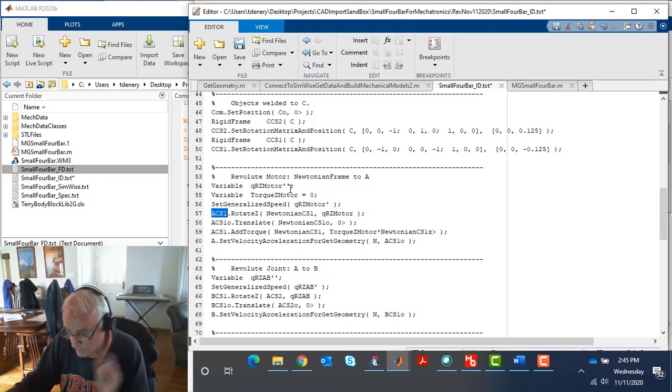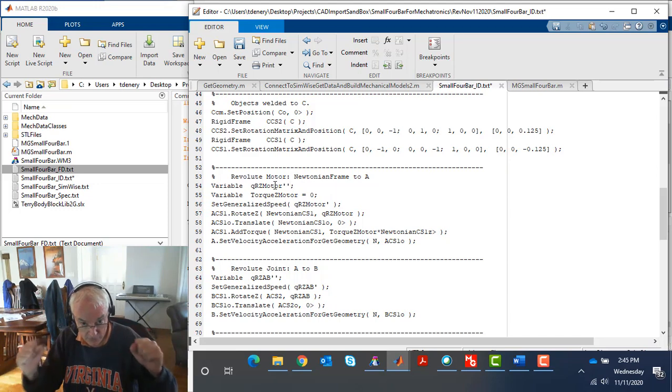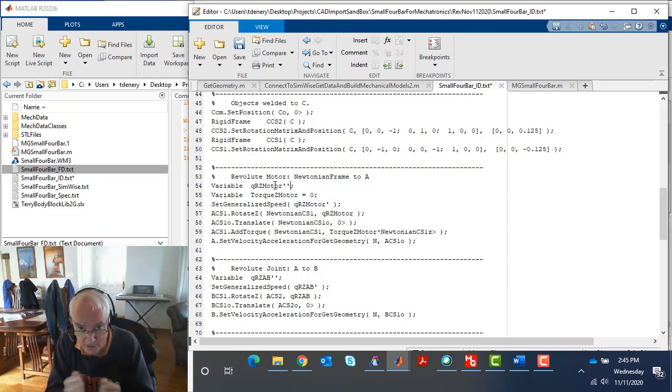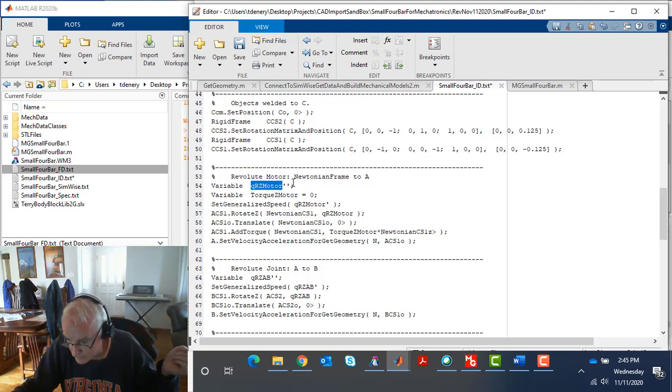Okay, now what I need to get into is this idea that those joints are real, they are moving, they are facilitating connection between parts, but they're not really degrees of freedom anymore. And that our true degree of freedom will be the motor angle. And that we're setting this up with our first joint, which we are calling the motor, right?